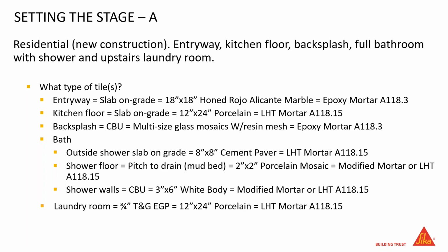Backsplash, CBU, multi-size glass mosaics with a resin mesh. We see a lot of that out there. We've had cases where we even have seen recently down in South Texas, we did a job, a courthouse, with a 1x2 split face that had a resin mesh on the back of it. And we used our epoxy for that installation. So we're using an epoxy to stick to that resin, so that way we make sure that we're getting a great bond with that.